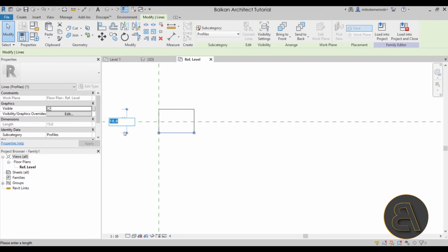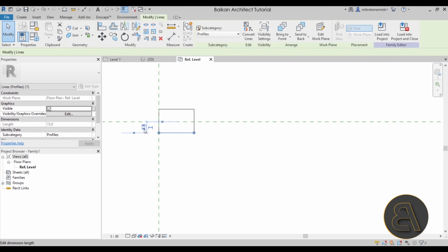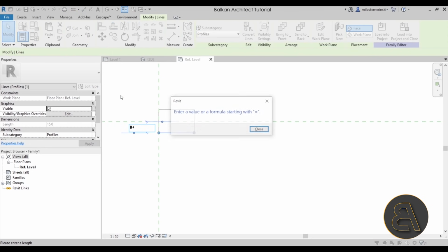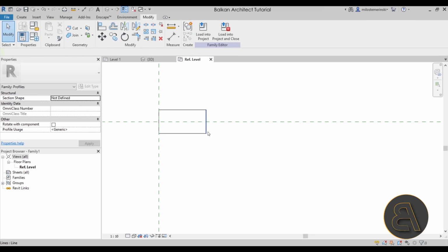So this is 1 centimeter or 10 millimeters thick. That's perfectly fine. Let's just make sure that it's centered. So this could be 5. Oops, that's not 5. Let's try that again. There we go, 5. And then that should be 10 in total. And the depth should be 20 to clear those 20 millimeters or 2 centimeters or 0.02 meters.